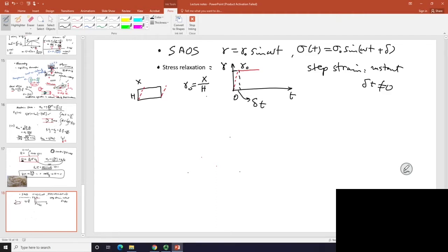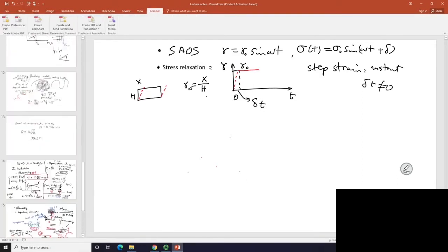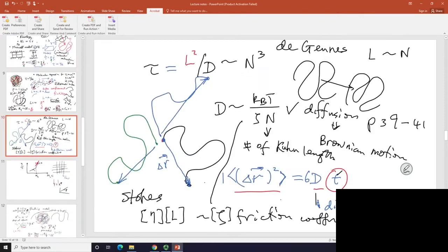Well, you quickly start to recall what we have known so far. The essence of viscoelasticity is internal time scale, tau. And of course, I didn't bother to tell you, we only introduced one relaxation time through the Maxwell model. There's a dominant relaxation time. We talked about repetition, where again, there was a dominant relaxation time that we only spoke about.